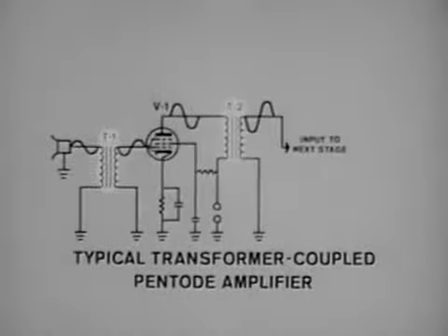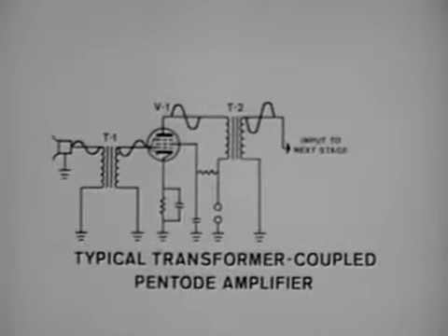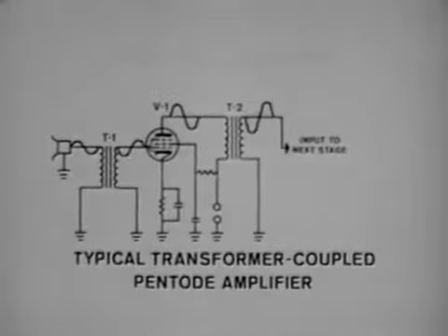One advantage of transformer coupling is that at lower frequencies, the step-up characteristics increase the voltage to a point where fewer amplifier stages are needed. When a transformer is used to couple between stages of amplification, it is called an interstage transformer.